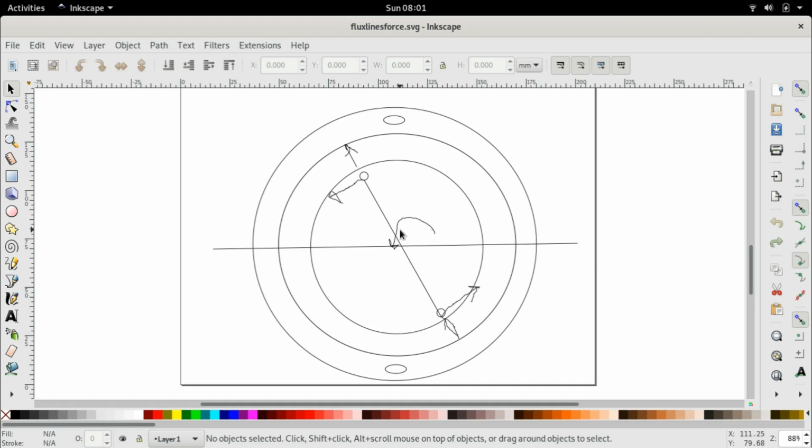And we have also seen, by using Fleming's left-hand rule, that the direction of the magnetic force is in the direction of this arrow for the upper rotor bar, and for the lower rotor bar, it is in this direction as shown by this arrow. And therefore it is very clear, because of these directions of the magnetic forces, a torque will be produced which will cause this rotor to rotate in the counterclockwise direction. Right? So this has all been discussed in the several lectures previous to this.